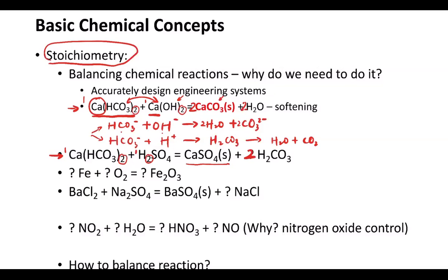So why don't we use that in water treatment? The major reason is because the sulfuric acid is too expensive, okay? For the other reaction, we're adding in calcium hydroxide, which can be formed by calcium oxide dissolving into water, right? And further, the calcium oxide just comes from the baking of limestone.